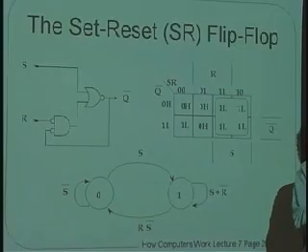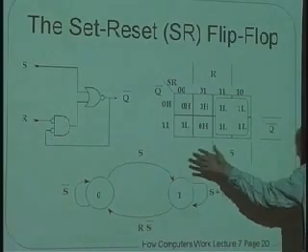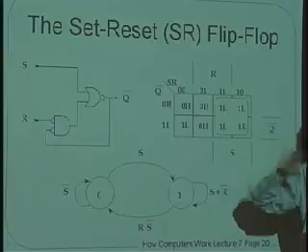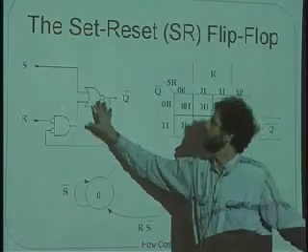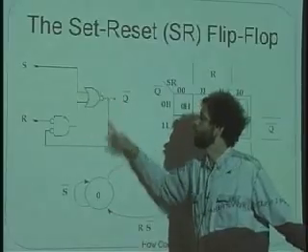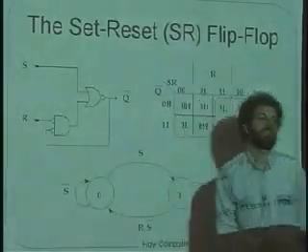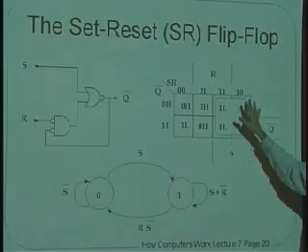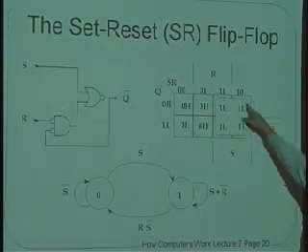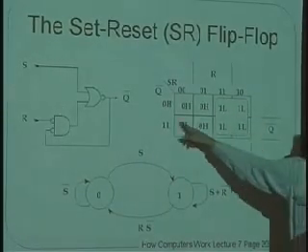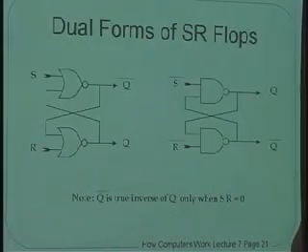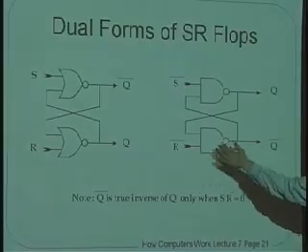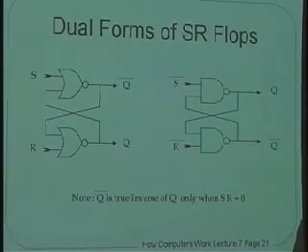Set, reset, flip-flop, okay? It's just a transformed version of the transparent latch that we're looking at here, and the general notion of a logic circuit with one bit of wire feedback is exactly the same. And the reason it works is, again, because the K-map, which has this term in it, and also one more here, which I haven't drawn in, is hazard-free. So this is just by way of things. Here's other ways that people draw the flip-flop. It's kind of a cool thing to look at. In your spare time, you should play with these things and see that they work the same way.